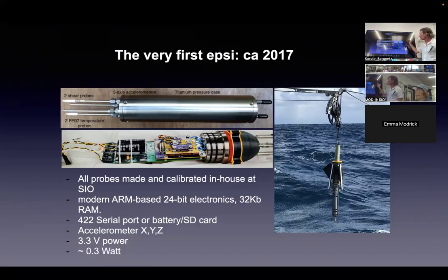And then this is our Epsi fish that you'll see. A lot of it's 3D printed. Again, we tried to keep it really, really cheap. But it has the same qualities as all those other vehicles that you saw in the photos. You need to have these drag screens that open, so it's basically like a parachute, and then it falls very slowly through the water and nicely controlled. And then they retract, so you can haul it back without a lot of drag.